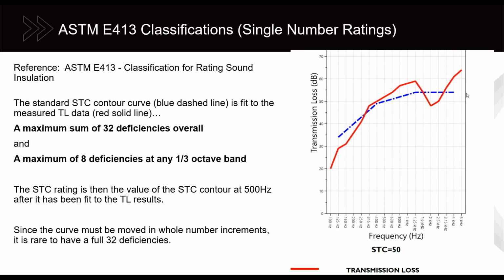So depending on your situation, acousticians will often want to see this 1/3 octave spectrum. For example, let's say you're building a wall that's a partition to block out sound, and you know that your noise source is very strong at 2000 hertz. Then this wall is maybe not the one you want to build, because it's weak at that single band, and that weakness is not really revealed in the STC rating.